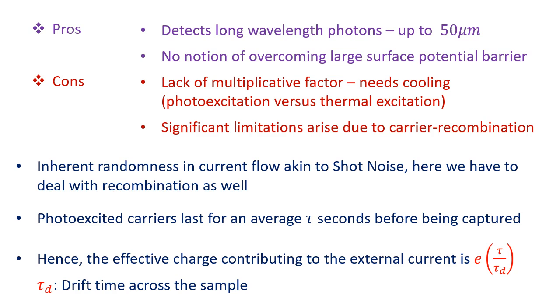Now there are problems. One of the biggest problems is that clearly you can see that these wavelengths are in the infrared, and hence the impinging photon flux and the thermal temperature of the device, the photons associated with the thermal vibrations, are going to compete with these external photons which you want to detect, right?